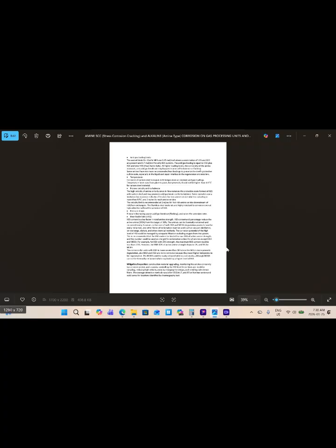Damage detection methods could be VT, visual test or visual inspection, guided wave UT, GWUT, and RT, radiography test, on hot-line amine service and weld zones, specifically weld zones with red lines, which are very suspect as high stress locations. And we can also do thermography tests with an infrared camera.